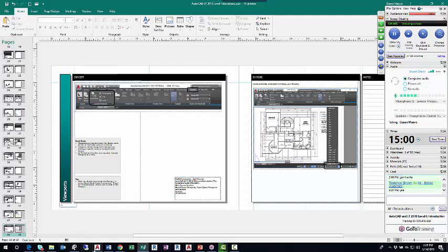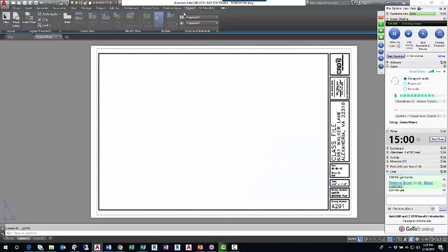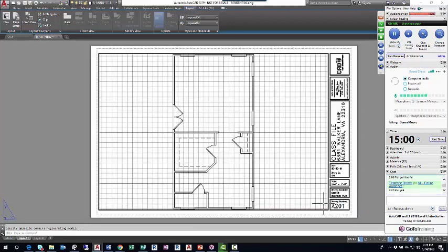So I'll do this in AutoCAD. Right, still in the layout tab. It's the layout viewports panel. We'll click rectangular, and it's just like using the rectangle tool that creates a polyline, but this creates a viewport. We'll go rectangular, left click the upper left corner of the border, left click the lower right corner of the border, and the drawing comes back, black and white.